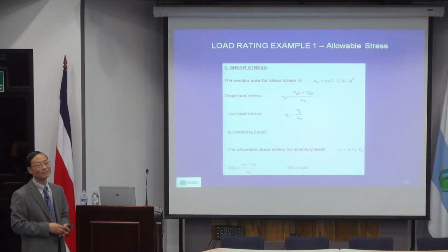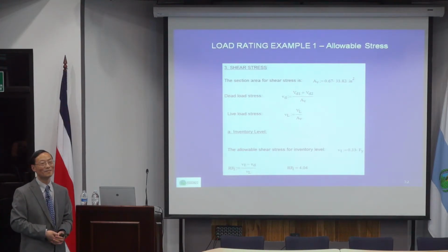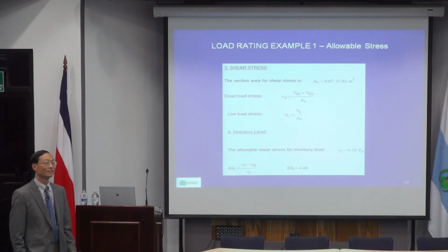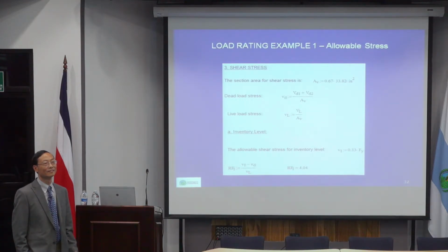Yes. So in this case, I understand I have to calculate all the elements. But if I make a composite of everything for a final report, when I calculate at least all the elements, I will know which element has a problem or not. But according to the phrase that I read, you have to evaluate the bridge with the lowest rating factor that you have. So for all the bridge, my question is, I understand that you have to calculate everything by elements, but if you determine the rating factor for all the bridge, you have to use the smallest one?